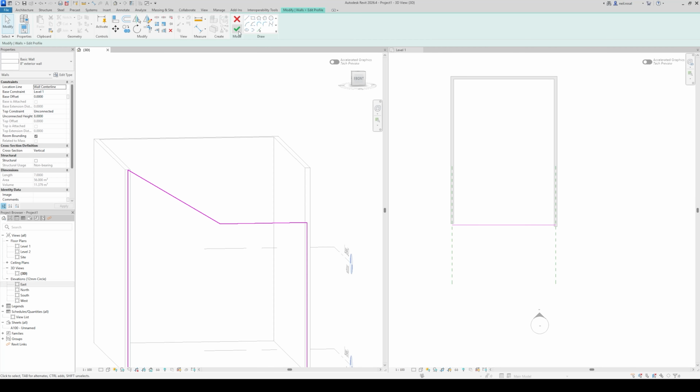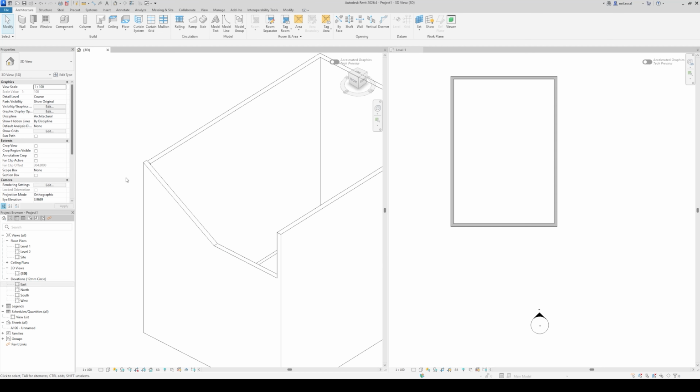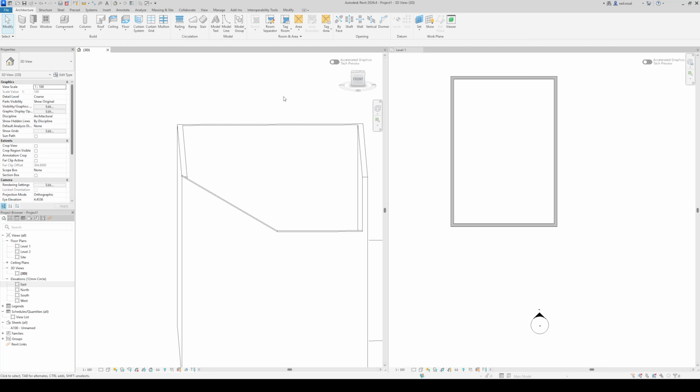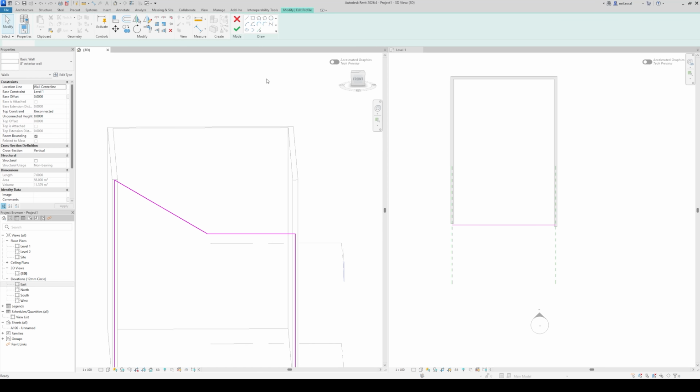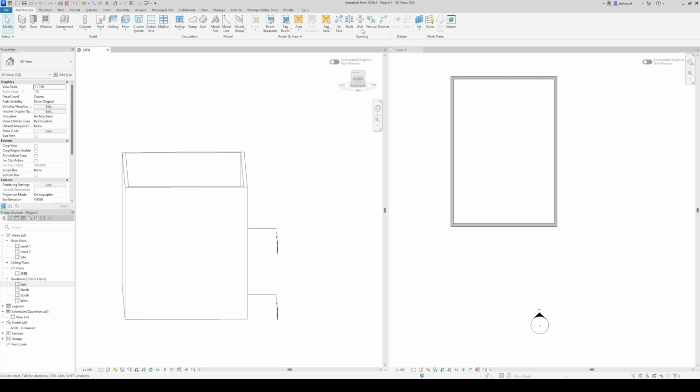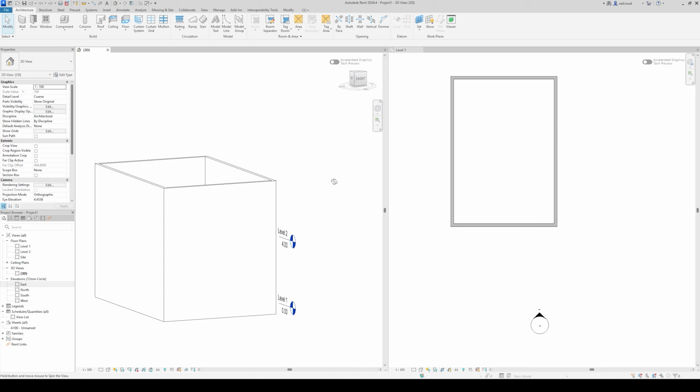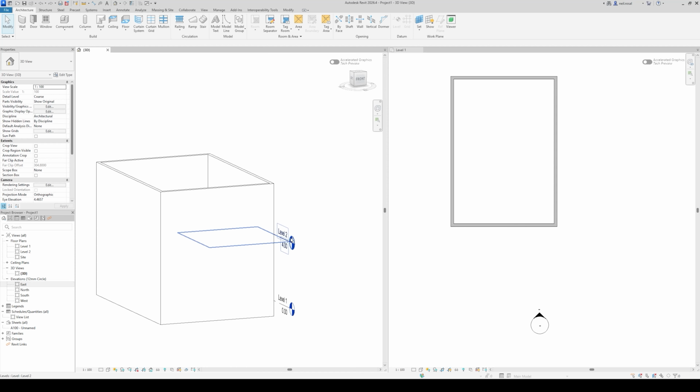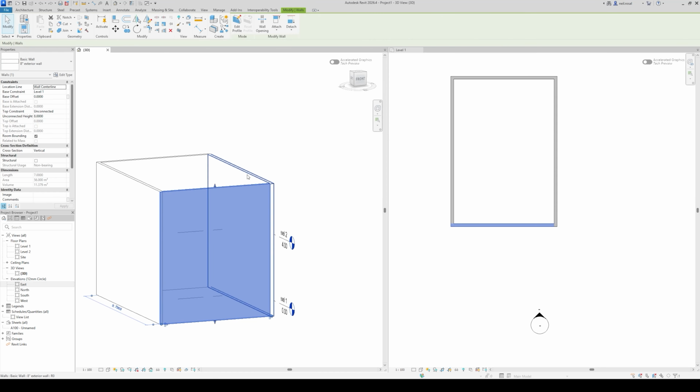And then when we go to the 3D viewport, we see this nice wall opening, but I'm just going to keep it simple. I just want a simple box. So now we have this space here for our first floor, the 7 meter by 10 meter first floor. Yeah, we want to change the heights for that to be attached to the level 2 of our project itself. You can change the height over here to that, but an easier way is to select everything.